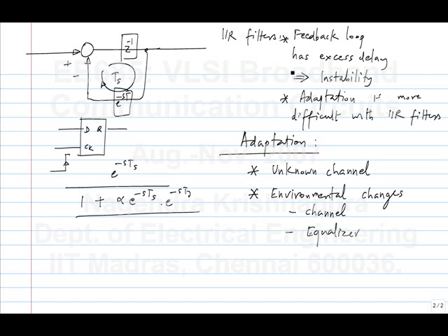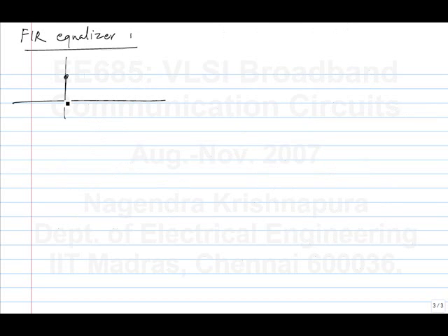So let's see what we can do with FIR filters. Let's say my channel consists of just one post cursor element, and everything else is 0. This is also just to get you a feel for what kind of impulse responses you need. It's possible to do everything mathematically, and if you do one general thing, everything is included in it, but it's also a good idea to know what happens in each case. You have a single post cursor ISI.